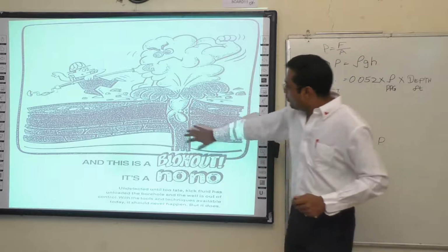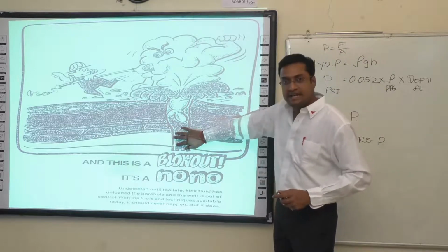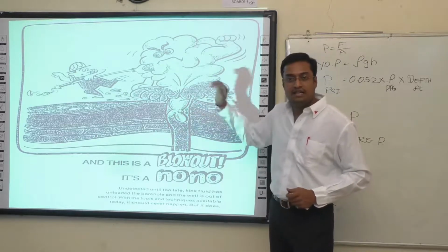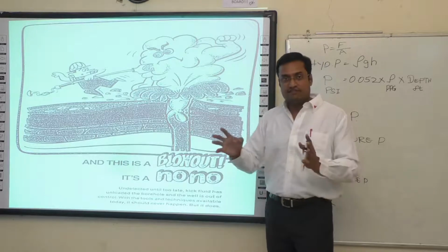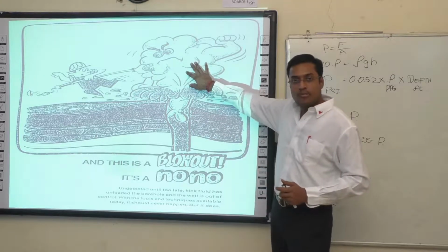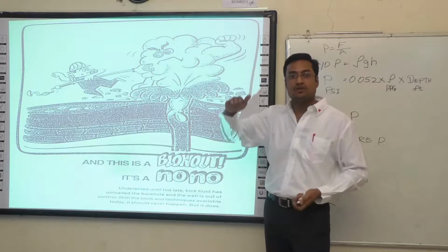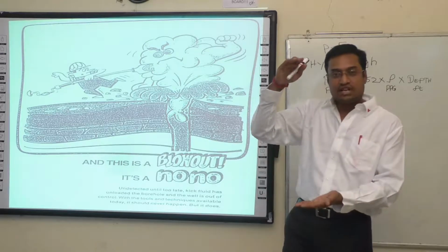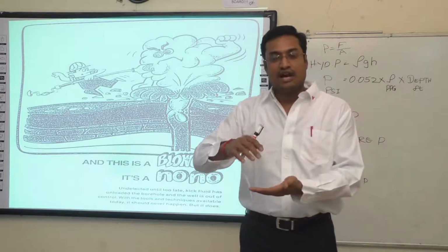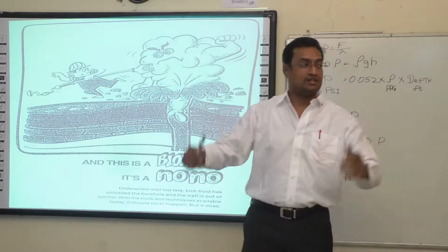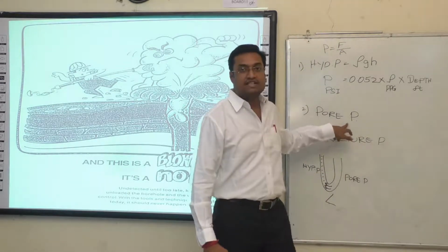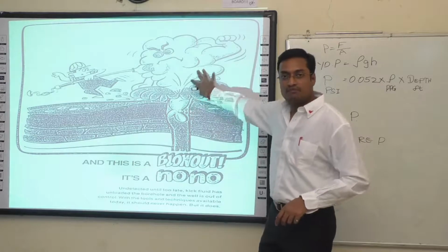That means, once a formation fluid gets inside, it will start replacing the drilling fluids. If the drilling fluids are completely replaced, the hydrostatic pressure starts reducing. When the hydrostatic pressure starts reducing, the underbalance condition becomes larger. The wellbore pressure takes complete control and it becomes a blowout.